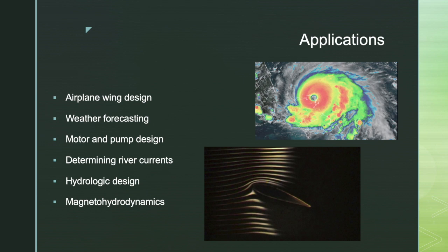The fluid regime, turbulent versus laminar, greatly impacts the heat transfer rate, and while there are approximations to model the effects of this phenomenon, this may be insufficient for high-performance applications, which makes the possibility of modeling turbulent flow with a high degree of accuracy very important. Turbulent flow can also cause cavitation, which can degrade materials, and there are many more examples of the usefulness of the Navier-Stokes equations.